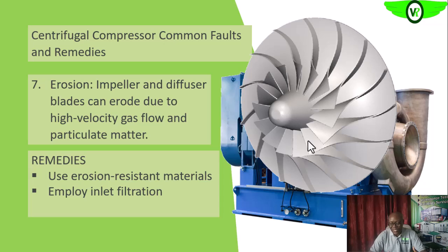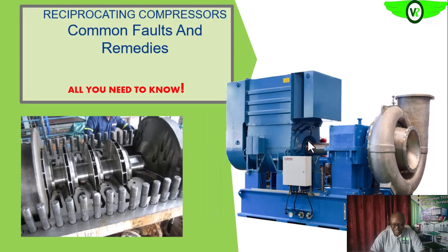Then we can reduce the amount of particles that is admitted into the compressor by using an effective inlet filtration system. Then we also want to operate the compressor optimally. Follow standard operating procedures to see that the compressor does not run outside what it is designed for. If we use it like that, we'll see that the compressor will last for us.